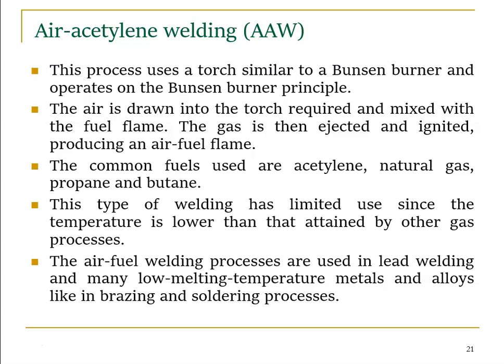So this is oxy-acetylene welding. Now we are going to see air-acetylene welding. The principle is the same. We are going to mix two gases. Previously we mixed acetylene with oxygen. Here we mix air with acetylene, but air has oxygen content. This process uses a torch similar to a Bunsen burner. It operates on the Bunsen burner principle. So Bunsen is a mixture, right?